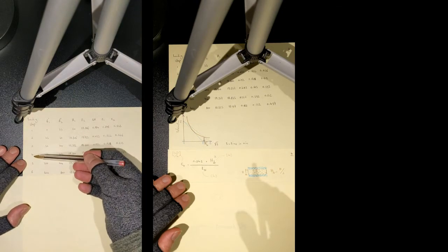So that's your secondary void ratio. And you can do the very same analysis for step 2, 3, 4, 5, and 6 to measure the secondary void ratio, which is the void ratio at the end of each loading step.